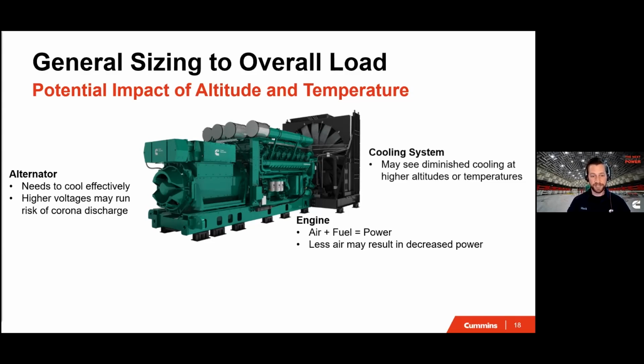Lastly, the cooling system that cools the engine through pushing air with that big fan you see on the right side of this image may also have challenges due to high temperatures and high altitudes for the same reasons as the alternator. Hotter and higher altitude air just simply makes it harder to cool the system.